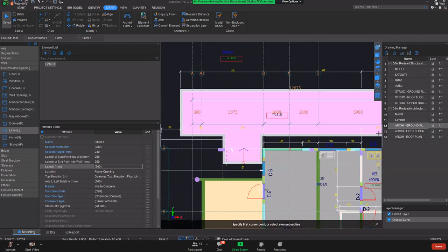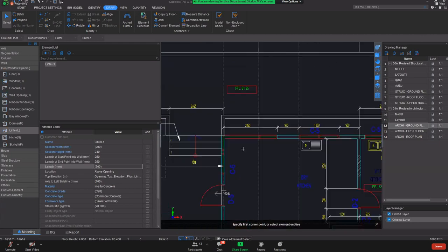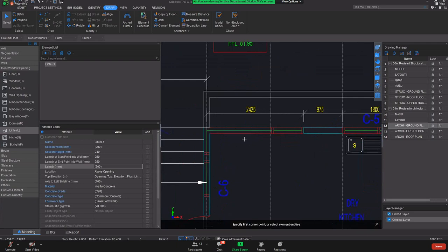Reason being, let me close off everything. If you can see from the drawing, yes, indeed, it's actually a window, but you will find that it doesn't have a label for it, right? And the software will not identify it if there is no window label. And also, there's some discrepancy, and if you encounter this, you might need to make sure with the architect what the code for this particular window is, and then only you're able to do the model inside, right?